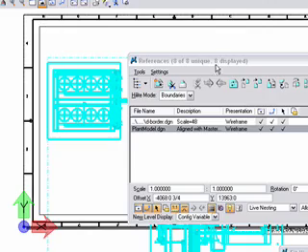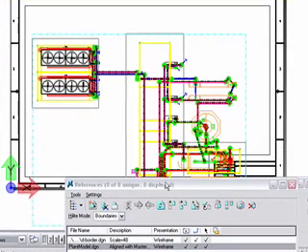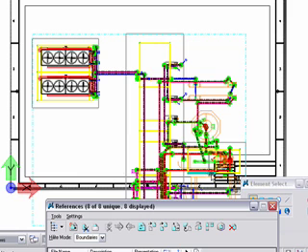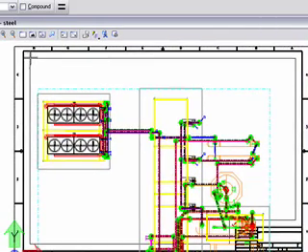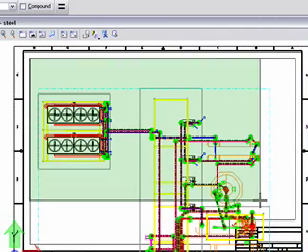And then again I'm coming into here. You can see that my model is now occupying the sheet I want, but there is bleed over on the model. In fact, I only need to have this cooling section here and the tower detail here. I don't actually need any of this stuff here. So what I can do is literally place a fence inside of my DGN.